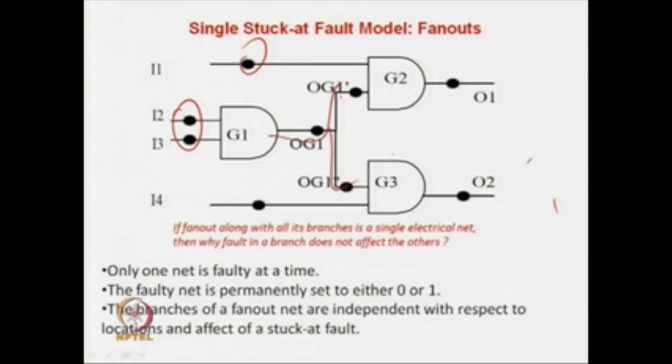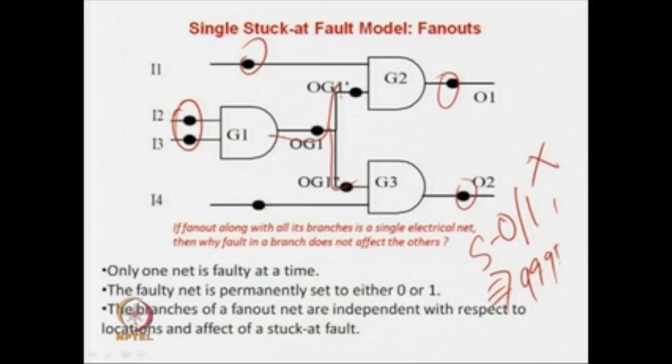We are not trying to ensure that our circuit is free of all faults, or to say that the circuit is normal. Rather, we are trying to say that our circuit has no stuck at faults, that stuck at 0 and stuck at 1 faults are not there. Then it implies there is a 99.9% plus chance that the circuit is normal.